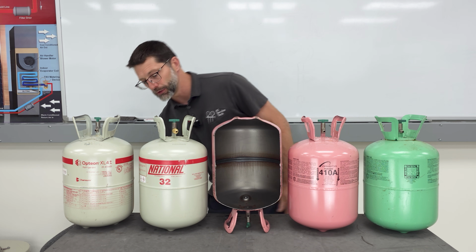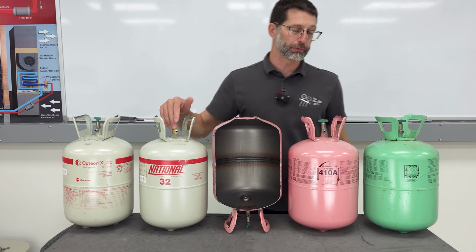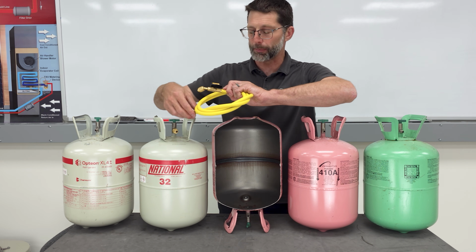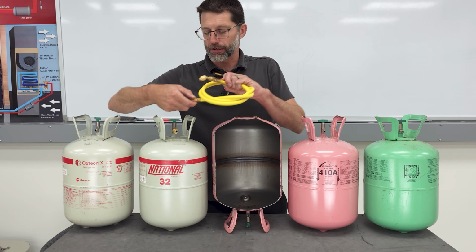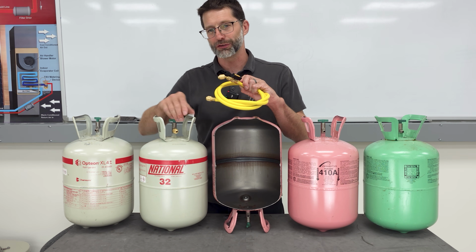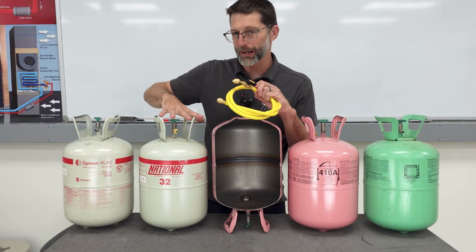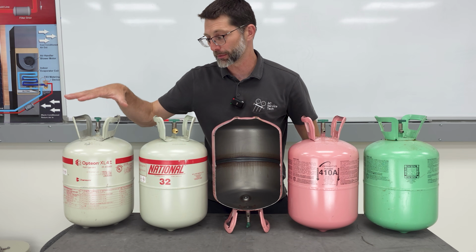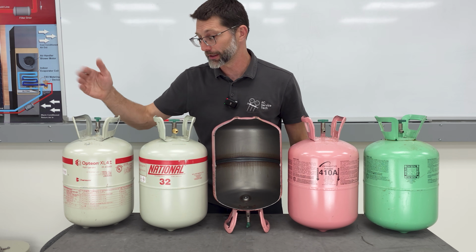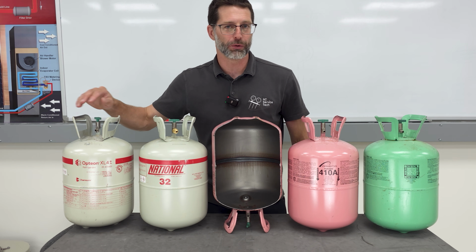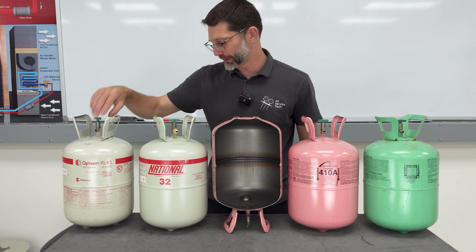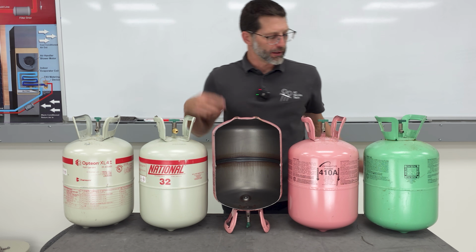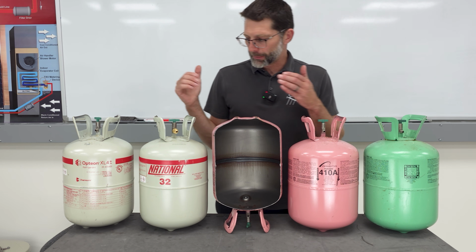Because you got to remember, if you add a left-hand to right-hand thread adapter and then you screw on a right-hand threaded hose, you have opposing forces, right? When you're trying to tighten this on, this one's loosening, so you got to make sure that they're both snug. And if this bottle is flipped upside down, like this one right here, which has to be flipped upside down when you're charging refrigerant out of it, it can become loose, and you don't want that. You want to have a tight fitting here, so you might want to use a hose that already has the left-hand adapter on it.